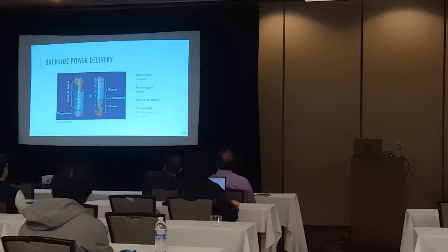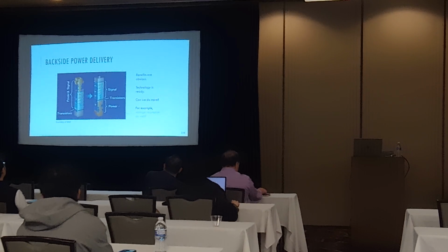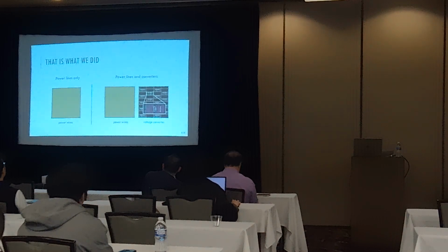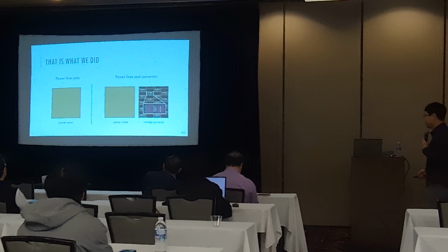But then what about adding some active devices on the backside as well to manage power conversion, voltage management? Is that possible? It's not as easy as just adding wires on the backside, because you need to add transistors on the backside. So we started looking into how that could be done. Again, this is what's happening right now: we have power network wires on the backside, and we have done some research on the feasibility of adding active devices there.